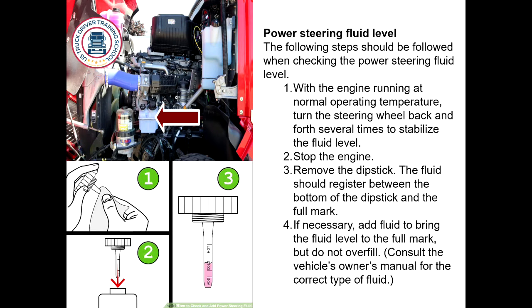Power steering fluid level. These following steps should be followed when checking the power steering fluid level. With the engine running at normal operating temperature, turn the steering wheel back and forth several times to stabilize the fluid level. Stop the engine, remove the dipstick.